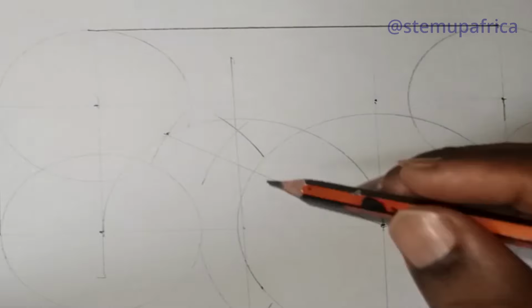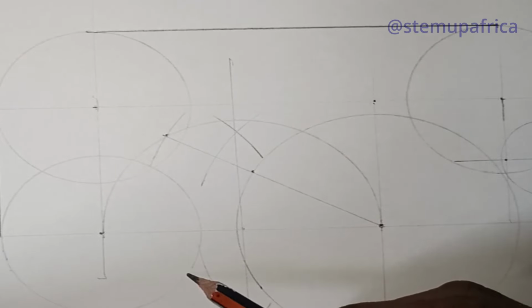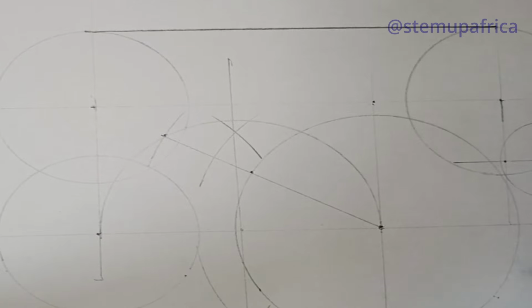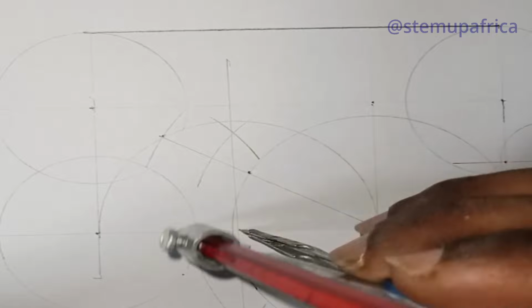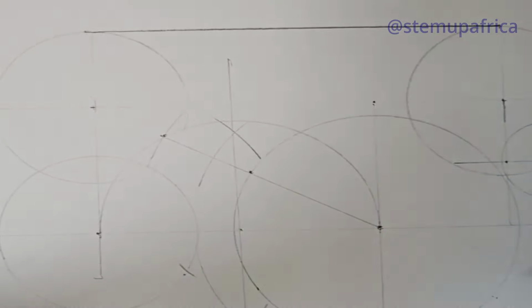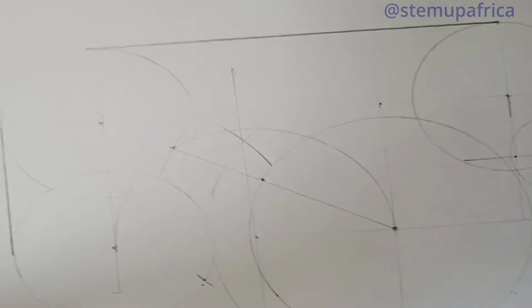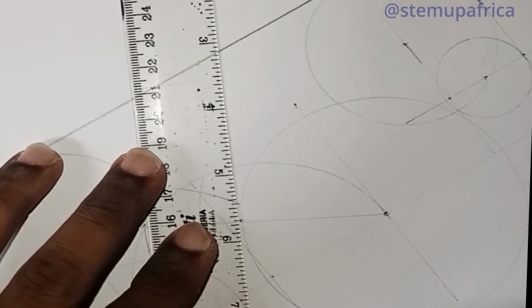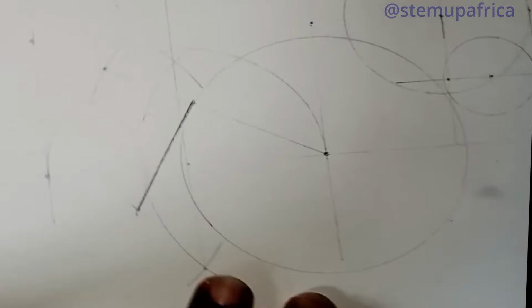So you see, this is the first point of the tangent. Remember the question says we should locate the exact point of the tangent. So how do we get the next point on this other side of the tangent? It's very simple to do. All you have to do is take your pair of compass at the center, extend it to the first point of the tangent, which is here, take it to this other side and cut an arc. So this is the second point of the tangent. With that, I can join both of them with a thick line. You can see it's perfectly tangential.